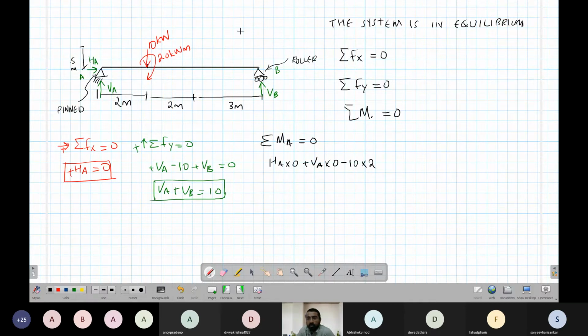When we say moment about any point, about this point, this point, this point, whichever point, the moment will be 20. The moment about any point in this will be 20. That will be clockwise, so it is minus 20. Now why is it 20 about any point? I will explain this once more. If you have a doubt about any point, the moment of a couple is the same moment. It is clockwise, so we have put the minus.